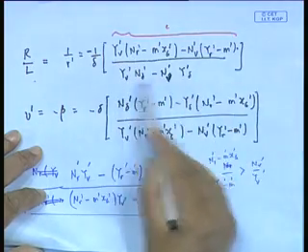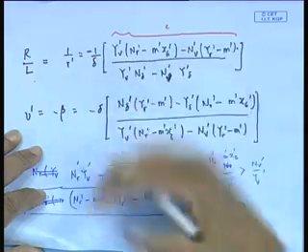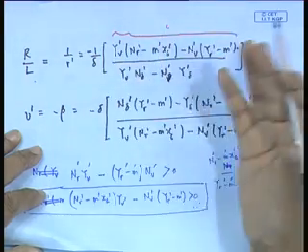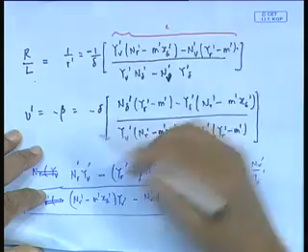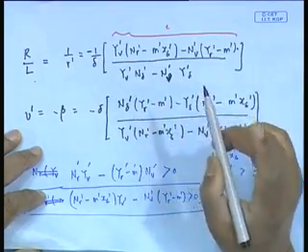These terms are all independent of ship speed. If I make it dimensional, it will be half rho L V square, etc., all of which will get cancelled from both sides. So interestingly, a ship going at 10 knots or 20 knots or 30 knots, if you give 30-degree rudder, will have the same turning radius.